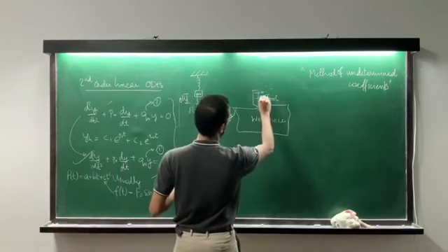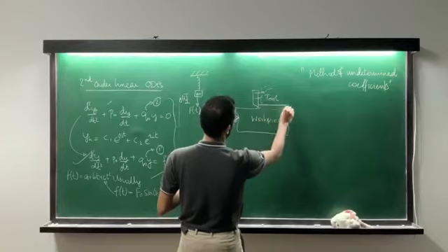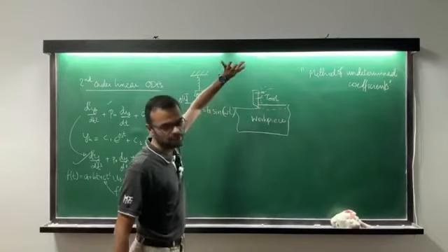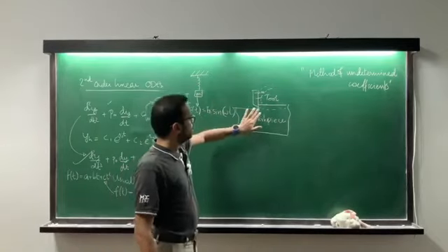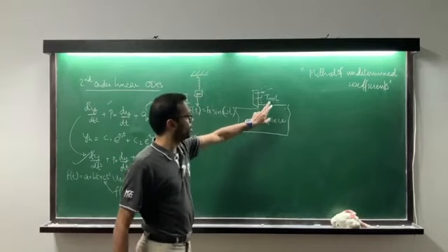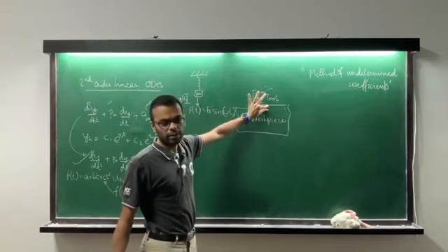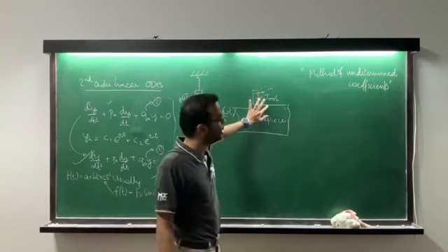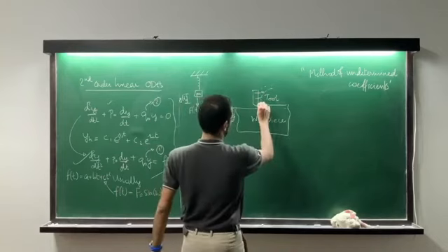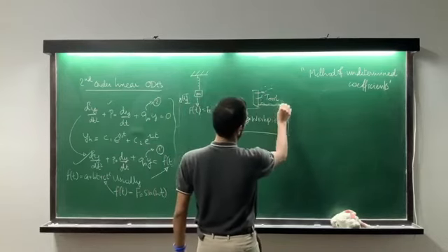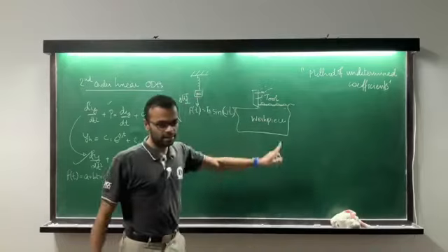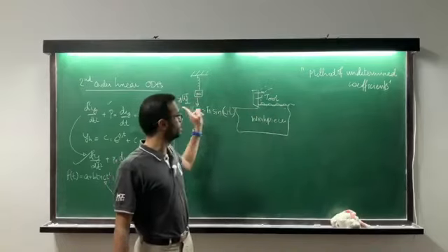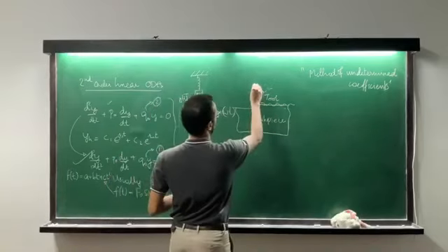You've probably seen this in workshop practice or whatever. This part of the material is being removed as the tool goes, and let's say the force on the tool is proportional to the thickness of the material you're removing. Reasonable enough, right? If the material has undulations like this, then this problem is the same as this problem, if the tool has some compliance.